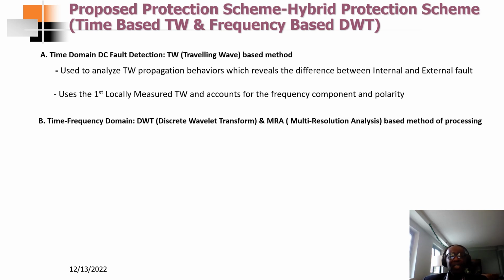Okay, so in addition to the traveling wave based method, I'm adding a time frequency domain, and in addition to that, utilizing discrete wavelet transformation and a multi-resolution analysis based method of processing. So this is the hybrid protection scheme, and that is the future of high voltage DC protection relays, right, to utilize a hybrid protection scheme.